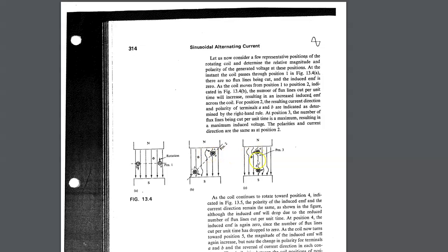They're just showing a couple, but I'm cutting the maximum amount of flux on conductor A and on conductor B. So at this position, we're cutting maximum flux, which means maximum force on charges in the conductor, maximum separation of charge, maximum voltage, and therefore maximum current at 90 degrees. Now notice the dot here on A and the X here on B. The max current is coming out of A going into B.